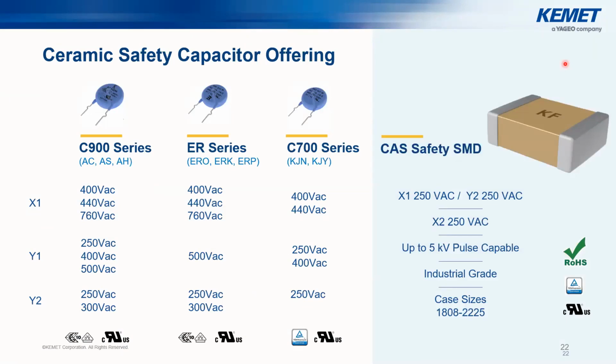So especially if you have any requirements for a capacitive voltage divider circuitry where you also need a safety rating for your capacitor, C0G is of course a good technology for that because of the low losses, low dissipation factor, and also the stability that the capacitor offers you. So if you need to save further space to avoid the THT part and use an SMD part, then for sure we have some interesting offerings from our SMD ceramic safety capacitor series.